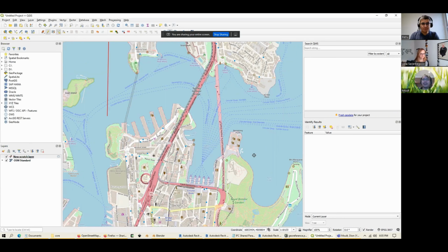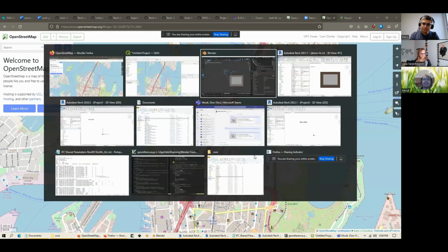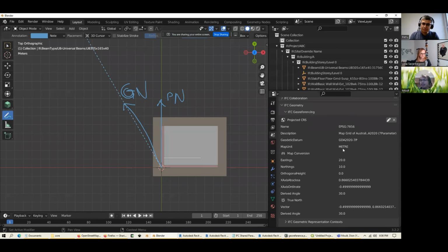So it's not a real meter. What that means is that there is a conversion factor from the distances that these eastings and northings are measured in, these map meters, and the SI meters that architects and engineers use on vertical construction projects.